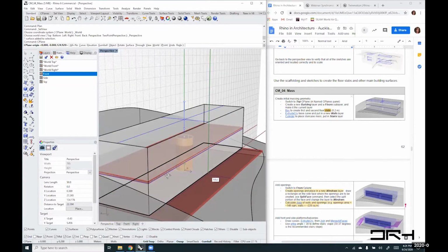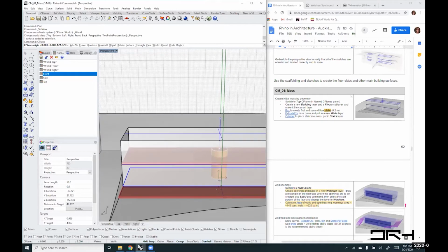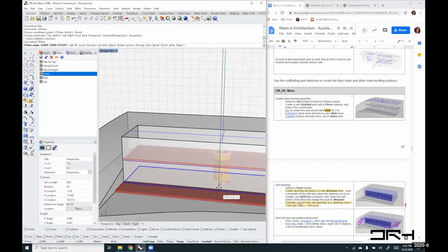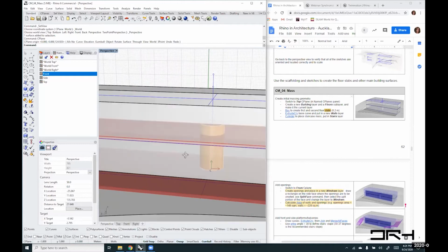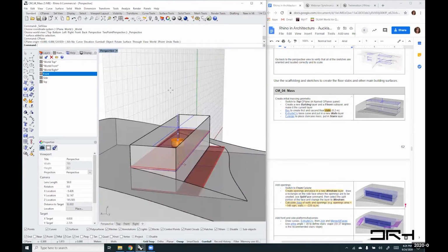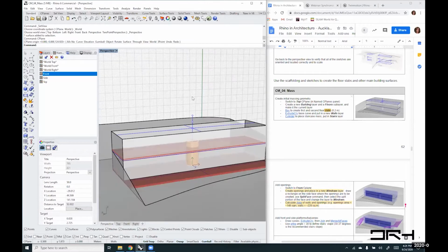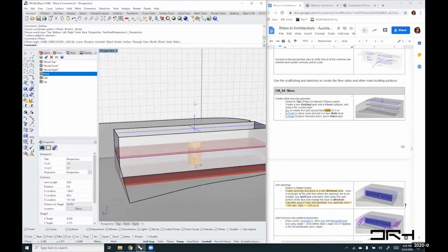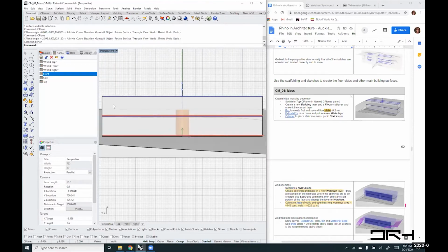So is that the mid? I just want to be sure here. Yep. And I want it to be here on the wall. So that's where my C-plane is, and this is where I now can go back and right mouse click to invoke my context menu to be able to have that view to easily draw any kind of openings I have here.